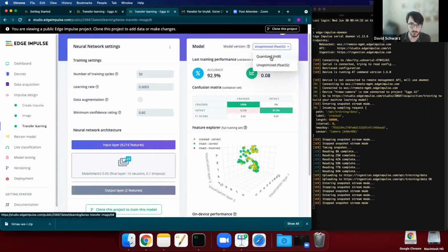So what we can do, and if you're familiar with the tinyML kind of tech, you'll know this is a pretty standard thing to do, is quantize the model, which means you scale down that range of floating point values to a 0 to 255, or negative 255 to 255 scale. And that gives you the memory benefit as well as the faster operations. And in a lot of cases, you won't actually see that much of a change in accuracy.